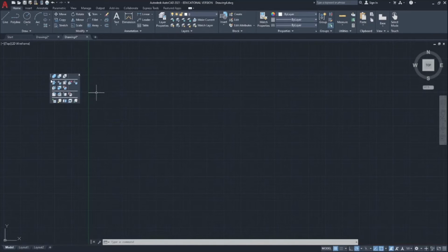So it's going to open up this little toolbar, and now that it's floating, you can see I'm just grabbing and dragging it wherever I want it on my screen. And it came in with my 5 rows, and you could, if you wanted, grab my little arrow if it'll let me here and just change the configuration if you wanted to. Although mine's not listening right now. All right, I guess I'm stuck with this. You should be able to grab and change the configuration. Otherwise, you could always go dash toolbar again, solid editing again, and then just type in a different number of rows. So that's how we dock it, and that's how we can free float it.